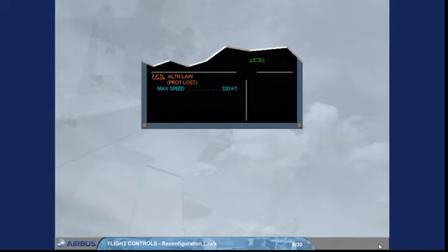Degradation to alternate law is indicated by an ECAM caution: flight control, alternate law, protection lost. A limited speed is indicated due to the loss of high-speed protection. Note: if the degradation to alternate law is due to a loss of 2 hydraulic systems, the limited speed will be as shown.